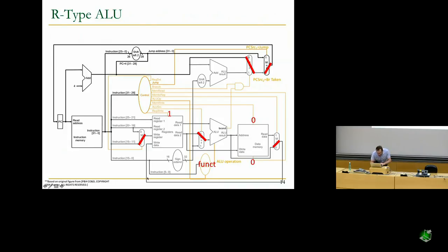So basically, ALU result should flow through this mux to the data input of the write register over here, the destination register. So this mux should be set to 1, which means that we're actually getting the ALU result to the register file and not the memory result to the register file. That's why the signal is aptly named memory to register. This mux is selecting the ALU result as its input to pass. Okay? So those signals are done.